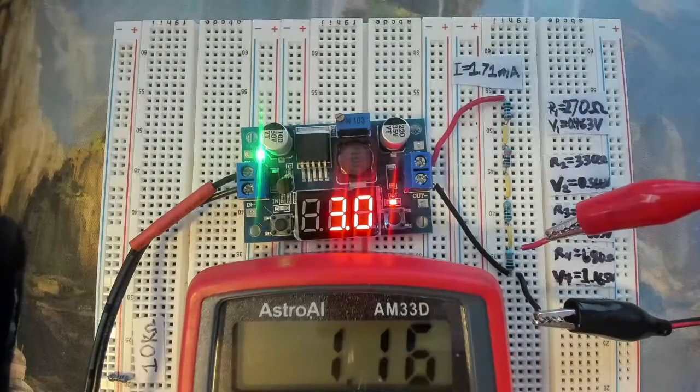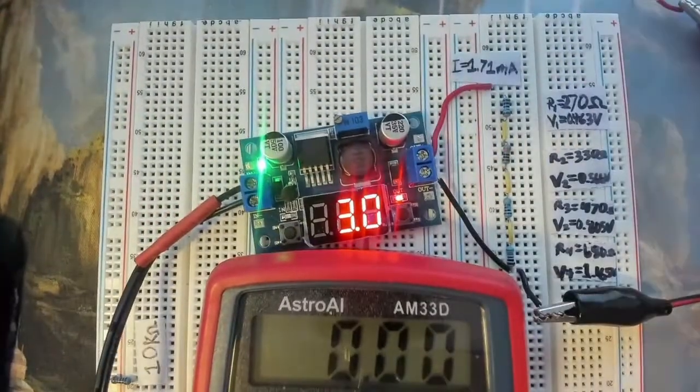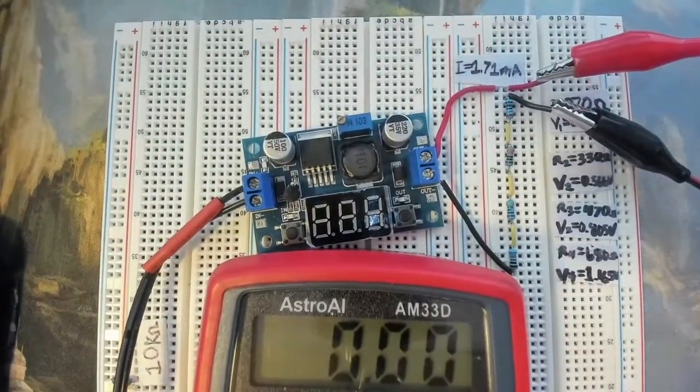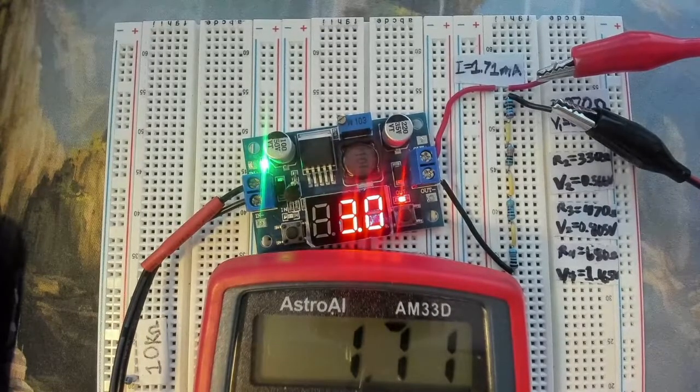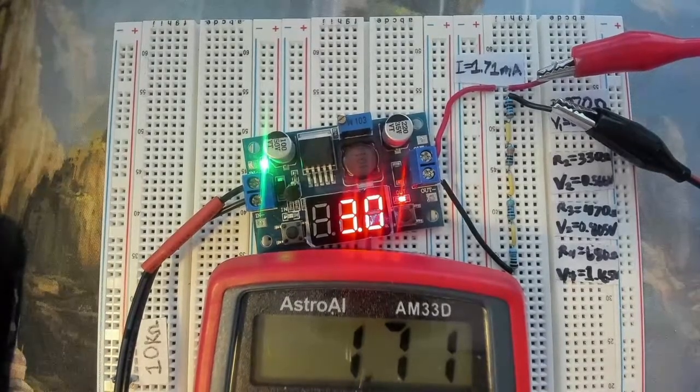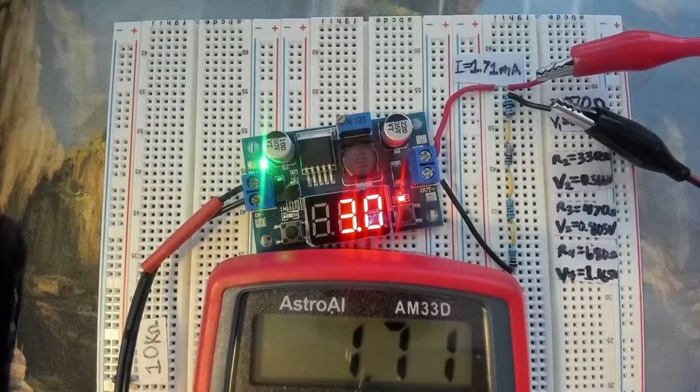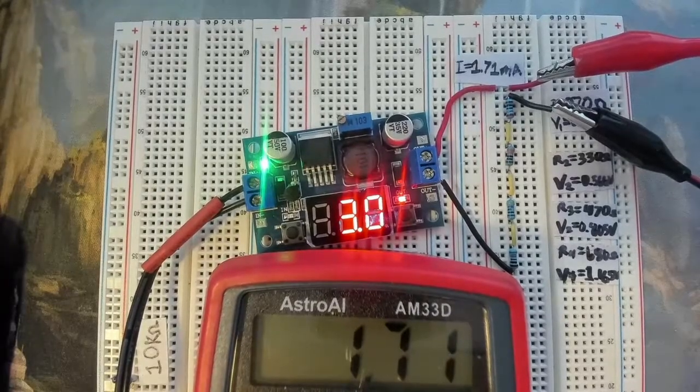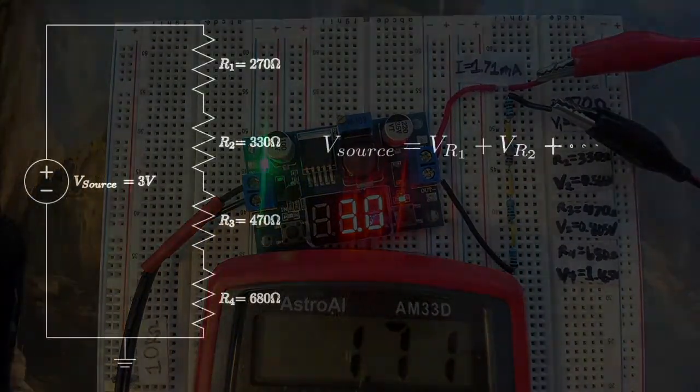Now let's measure the current, and if this is the same voltage and current for each of these, we've also done a good job at determining how much power we're probably going to be using in the circuit. Okay, I hooked up the current to see how much current we're measuring, and we see that we have 1.71 milliamps, exactly what we calculated. So as you can see, for the voltage divider with resistors, our theory is very accurate to what we are measuring in reality.